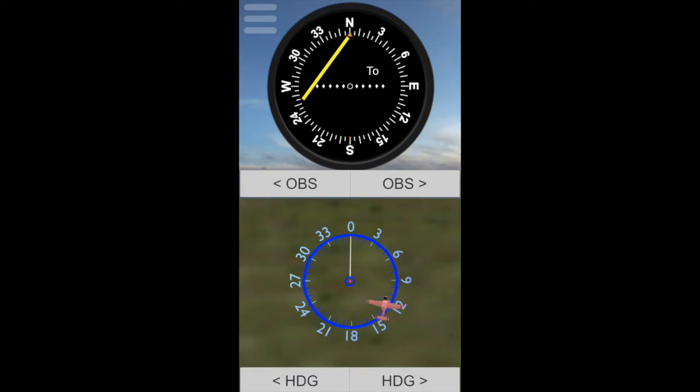And one more thing you need to pay attention to. Your aircraft heading doesn't mean anything here. Look, the aircraft could be turning around like this. Doesn't matter. Imagine your aircraft being like a dot, like a little point, and what matters is whether that point is on the radial or not. Your heading is not a factor here at all for the indication you're going to get on your CDI, course deviation indicator, that you see on the upper half of this illustration. Back again. Anywhere here, it's still a to. Anywhere on the top, it's a from.